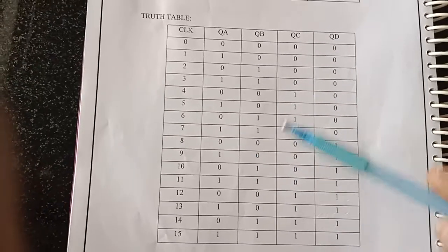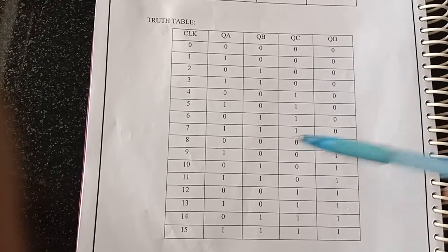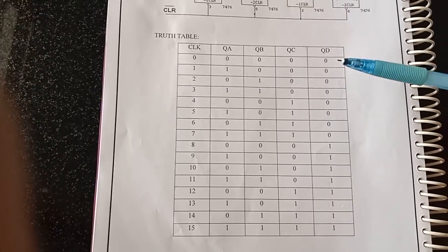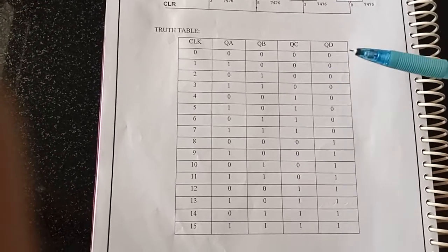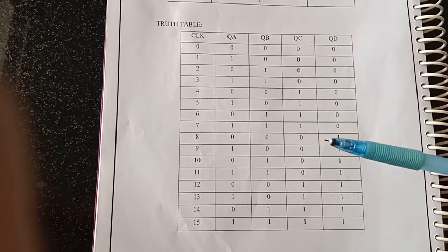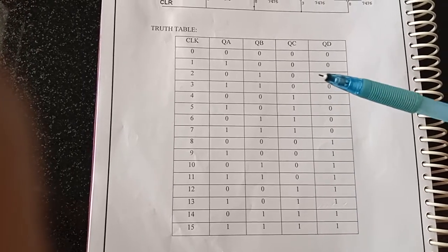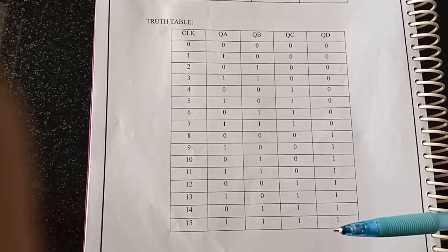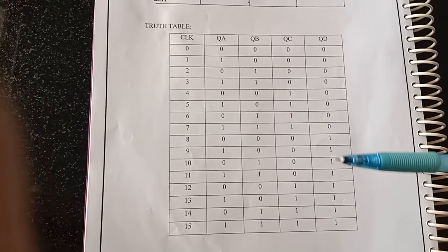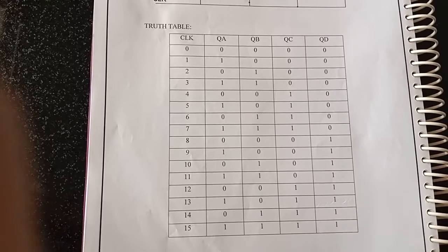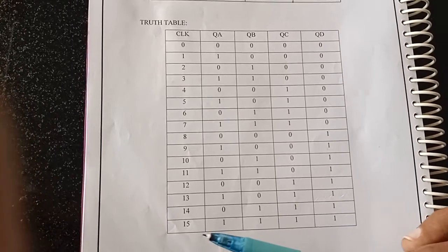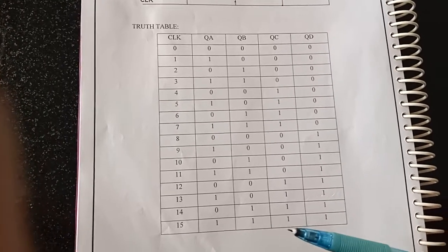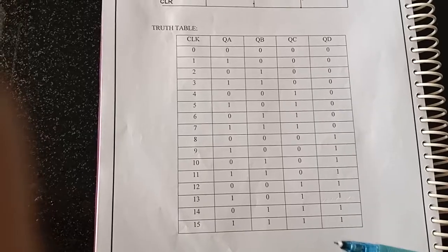So in this case we are going to apply the clock pulses. Our 4-bit ripple counter automatically counts the clock signals based on the input clock pulses. This is the output in binary value. In this 4-bit ripple counter, we apply clock pulses from 0 to 15, so it counts the clock pulses as per the 16 combinations, 0 to 15. The final value, if you apply the 15th clock pulse, is that all the values are equal to 1. That is 1 plus 2 plus 4 plus 8, so the total value is equal to 15.